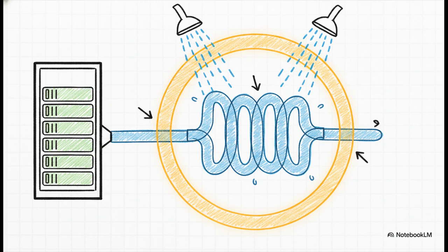You absolutely cannot afford even a speck of dirt, scale, or debris getting into your unbelievably expensive internal chillers. Well, enter the closed-circuit coil. This thing is the ultimate data center savior. Instead of exposing the server's precious cooling water directly to the outside air, the water flows through closed copper or galvanized steel coils. The cooling tower just sprays its external water over the outside of these coils. This keeps your internal loop perfectly isolated, pristine, and totally safe from contamination.